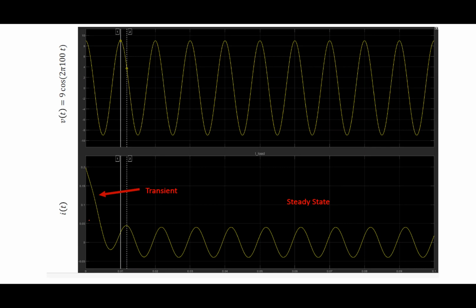That's one area. Another area you might think of is when I have a motor, for instance. Let's say I have a motor that's 100 horsepower, right? That motor is going to draw about 100 amps when it's in steady state. It's going to draw about 700 amps when it's starting up, right? And so I worry about those kind of transient behaviors to figure out what that's going to do to the voltages all throughout the grid and things like that.